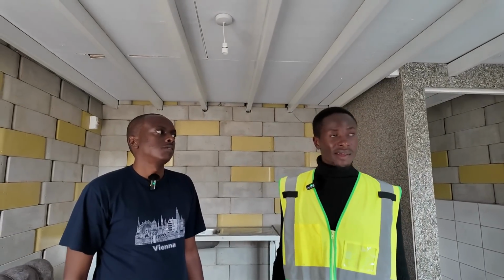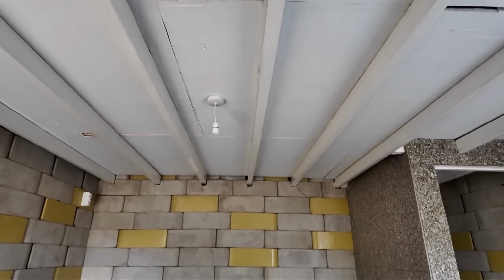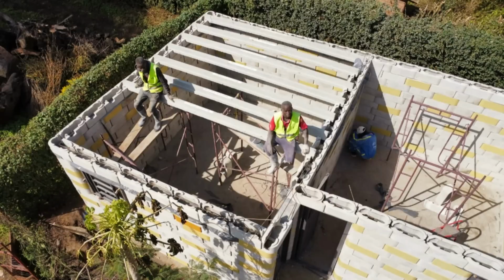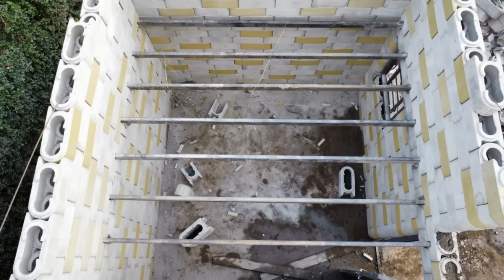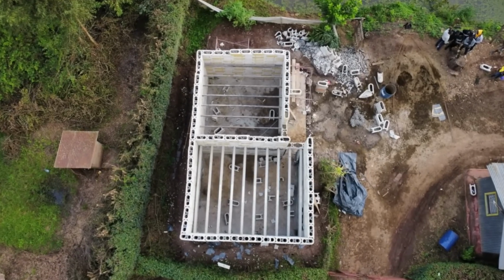Okay. Well, in this room, the roof itself, or rather the ceiling, is very different from the other one. The other one, you had utilized T-beams. For this one, we have utilized rectangular hollow sections. So they are the ones which have held the marine boards, and then on top of the marine boards, we have a very good finish. So both of them have a concrete finish atop of them. It's only that we are exploring which option is more affordable. So this one proved to be more affordable than the precast beams.